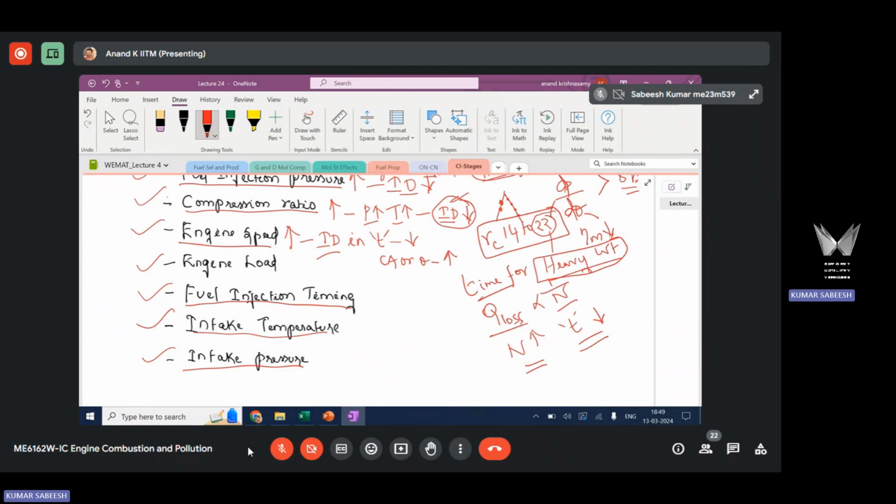It will reduce the delay, because you have more heat. When you inject fuel and there is more heat in the cylinder, the overall delay time is going to come down, isn't it? One important effect of engine speed is that you are not giving enough time for heat loss, so you retain more heat inside the cylinder at higher engine RPM. That will reflect in a shorter ignition delay in terms of absolute time.